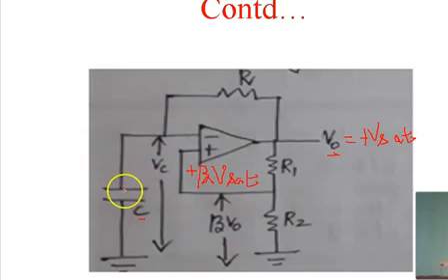Now, again the capacitor starts charging and keeps on increasing. If the voltage across the capacitor is greater than or equal to beta V sat, the output voltage is equal to minus V saturation. Like this, the process repeats, and finally we get a square wave at the output.